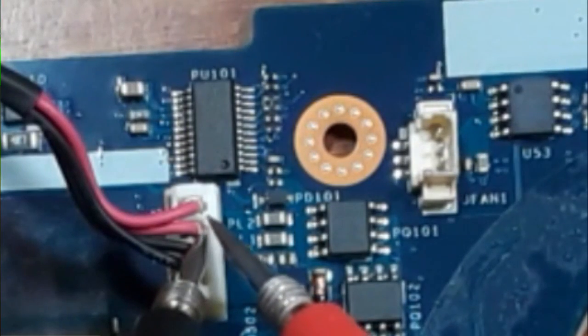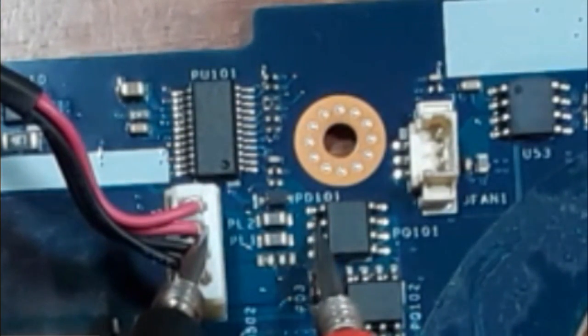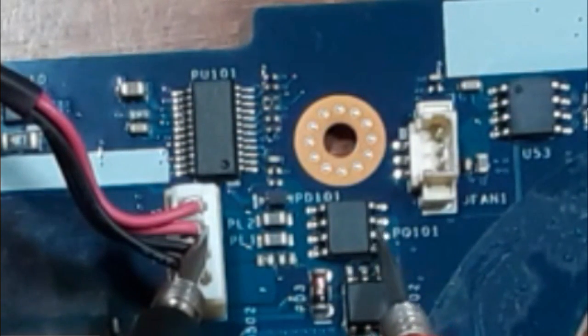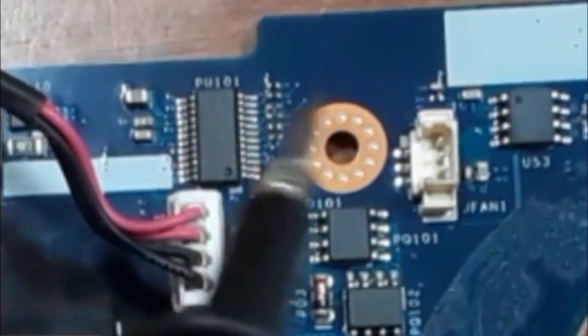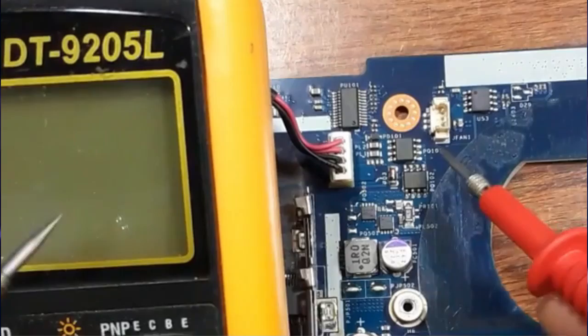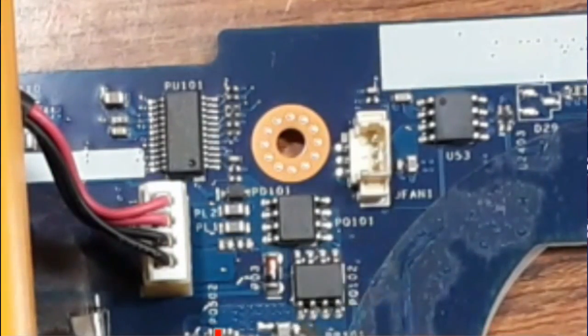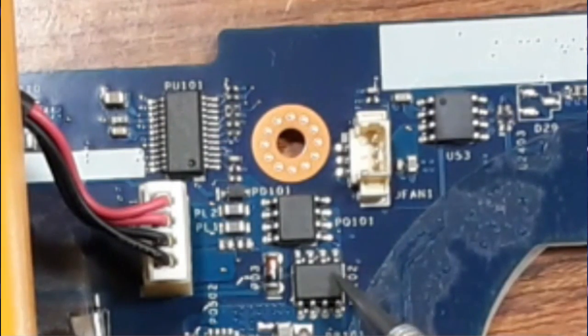So now the 20 volt should pass through these coils and then go to the drain, to all these 4 pins, and then should pass to the source. The gate here should receive the control signal from the IC. Okay, and then as you can see, the source of this MOSFET is connected to the source of this MOSFET. Here we have the point, as you can see, which means this is pin number 1, 2, 3.